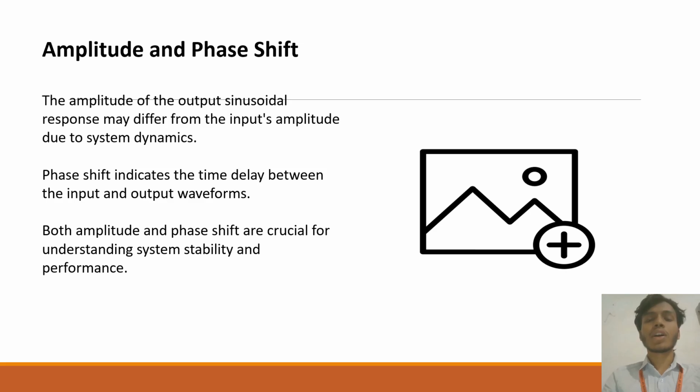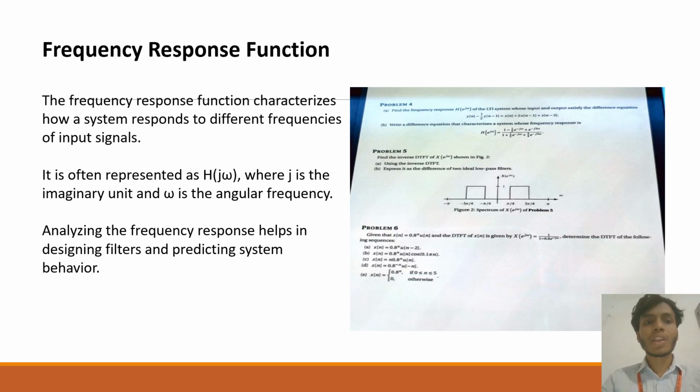Amplitude and the phase shift. The amplitude of the output sinusoidal response may differ from the input's amplitude due to the system dynamics. Phase shift indicates the time delay between input and output waveforms. Both amplitude and phase shift are crucial for understanding system stability and performance.